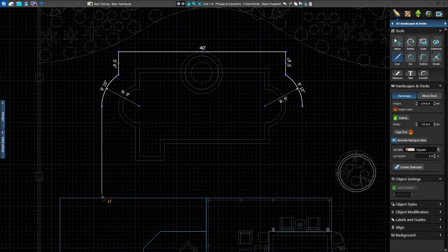Now we'll switch to the line tool to draw down 22 feet to reach the first hardscape we drew. We'll draw to the right 48 feet and left click. We'll see the autocomplete target line appear. We can draw up to complete the shape or click back on the last point to use autocomplete. We'll set the height to 0 feet 0 inches so it's flush with the ground and the pool.